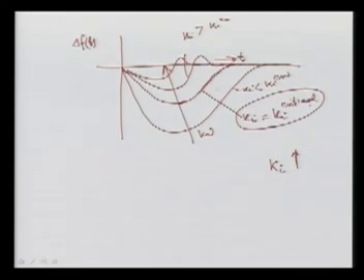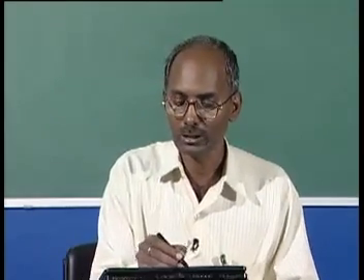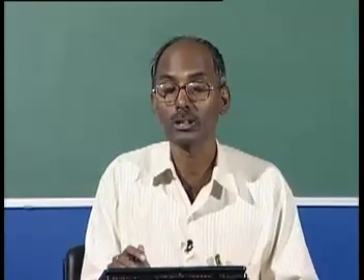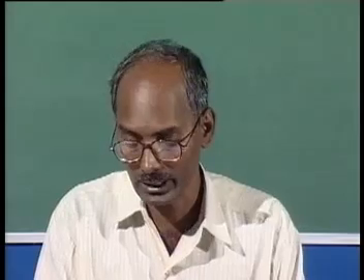You can see here we are just getting the zero steady state error, but we have to see by setting the value of Ki, that is very important, and that can be changed because it's a controller gain. Then your performance time is also changing. Here this is the settling time. So we want to see how much overshoot and how quickly it is settling. So the Ki is a very important parameter, and once we calculate the critical value, then whether we increase or decrease it, you can achieve the performance accordingly.